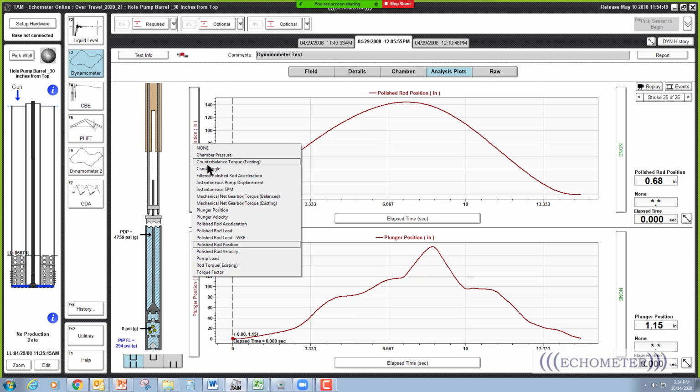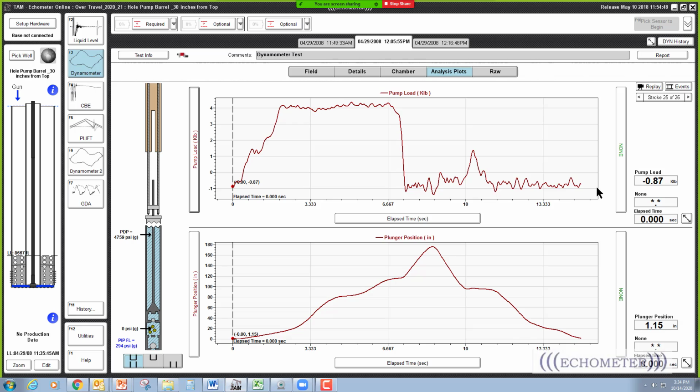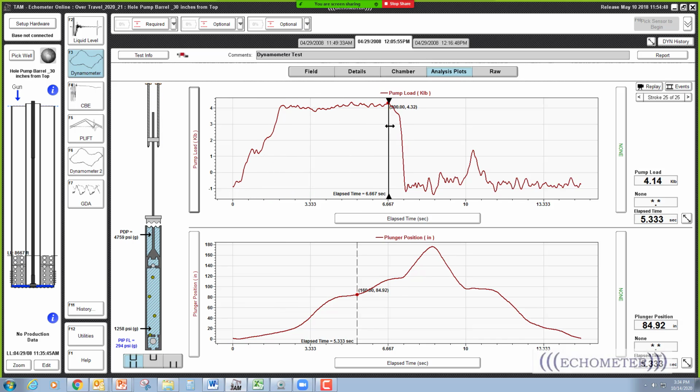and we plot the pump load here, again, you can see that spike load right there, which I'm wondering isn't it hitting at the top. But what I was wanting to show you is that if you come right here and you look at that point right there where the load drops off is 7.13 seconds, and then down at the bottom, that time is about 0.2 of a second.